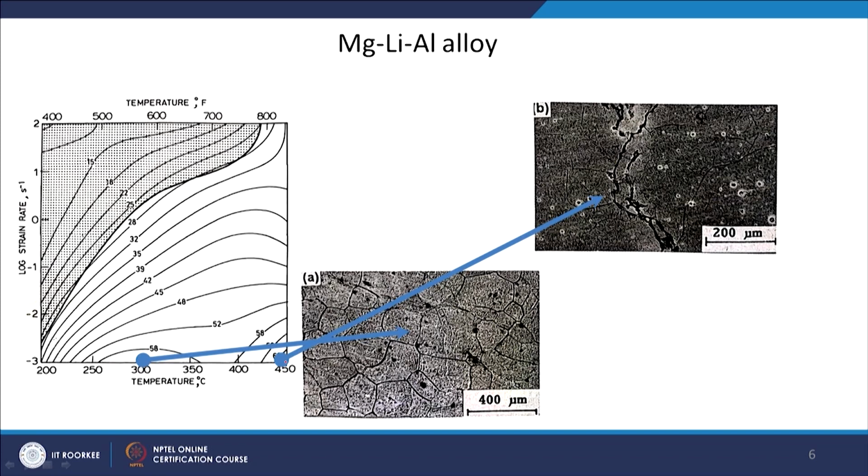So, with increase in temperature you have a new type of defect, and you can also see, if I am not wrong, that some cavities have formed here, maybe on the grain boundary, and you can also see this kind of cracking or cavities joining together, and you have a cavity coalescence kind of phenomenon. And maybe some wedge cracking also must have taken place.